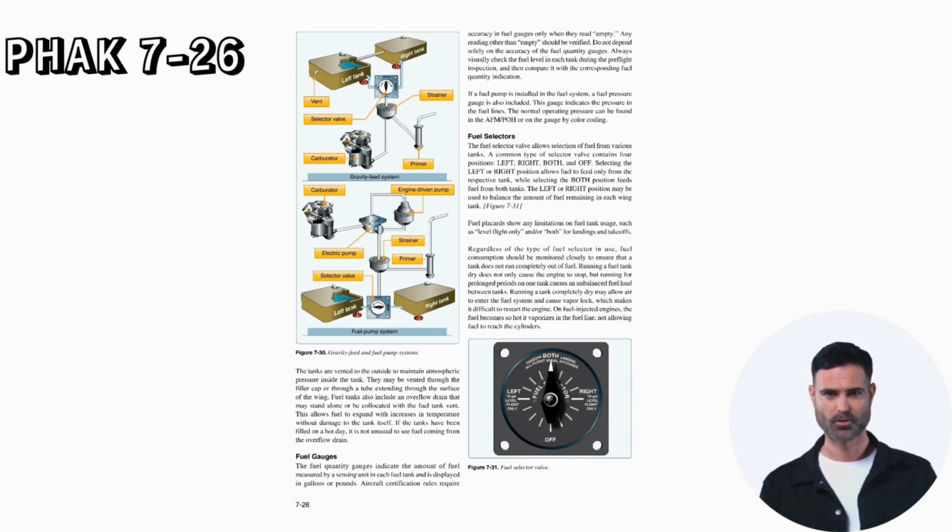Regardless of the type of fuel selector in use, fuel consumption should be monitored closely to ensure that a tank does not run completely out of fuel. Running a fuel tank dry does not only cause the engine to stop, but running for prolonged periods on one tank causes an unbalanced fuel load between tanks.